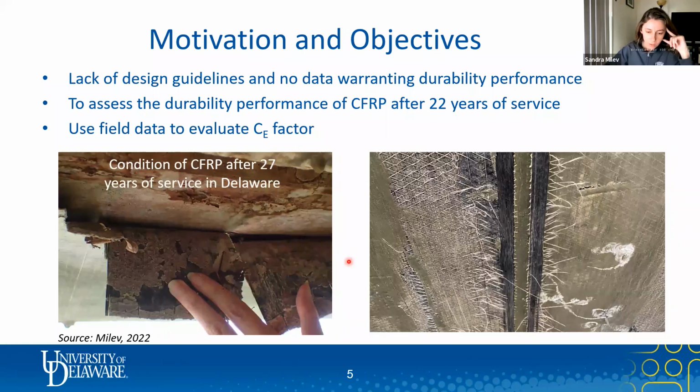So for this one, it was repaired in 1994, and the intention was to extend the service life of the bridge only for 10 years. And now it has been almost 30 years after. So I think in a way this was expected, especially as Ajay said, the surface was not coated, and there was a lot of moisture and water seeping through the joints and everything.